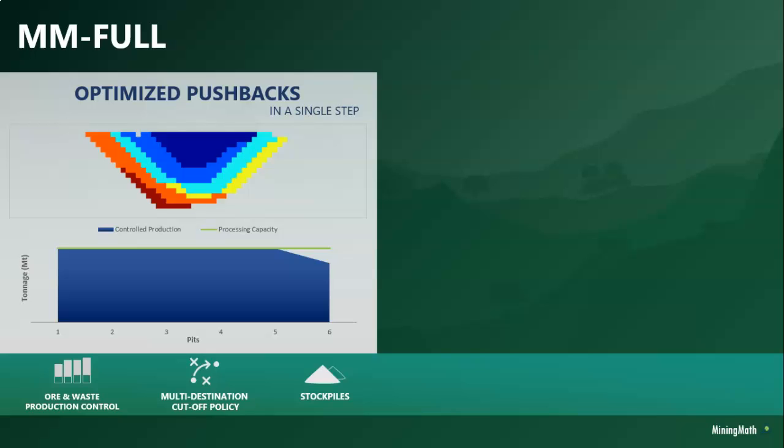Here we can add a limit for stockpiles. You can add constraints based on average and sum. So for example, you can put constraints related to the grade, to material type, to hours of equipment, every kind of constraint that you can imagine, you can add here. And here we can also add force mine and restrict mine.